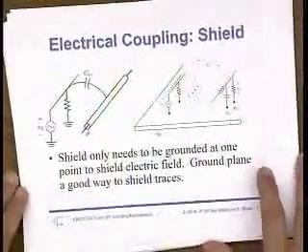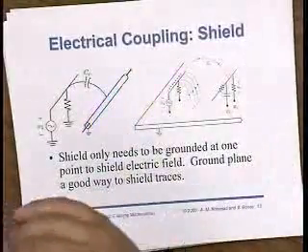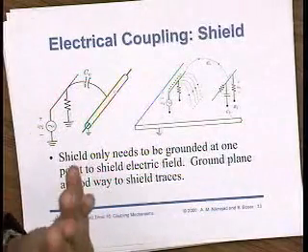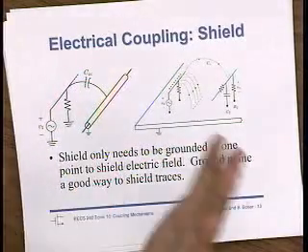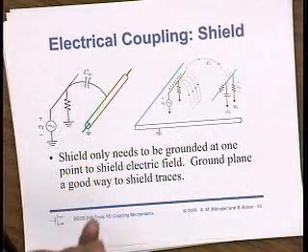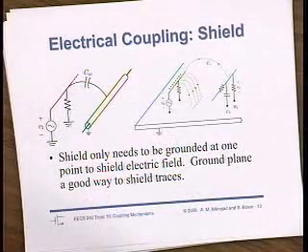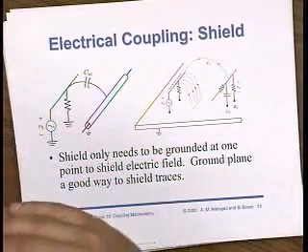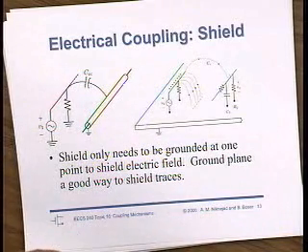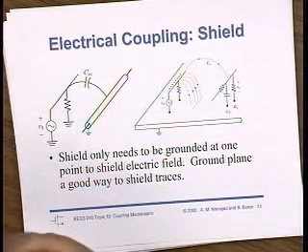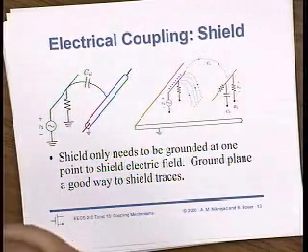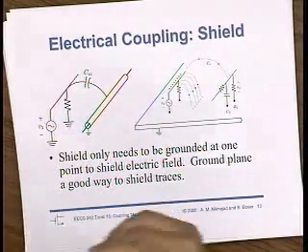Okay, the other thing to consider is when you design circuits and you're worried about coupling, there's two kinds of coupling that you would worry about. One is, well, there's actually many kinds, but let's talk about two kinds for now. There's electrical coupling, and it's very obvious. Electrical coupling is just capacitive coupling. So in theory, everything is capacitively coupled to everything else. If you build a board, every piece of wire is capacitively coupled to every other piece of wire, right? No matter how far you put them away, they're still coupled. And there's a couple of ways to reduce that coupling.